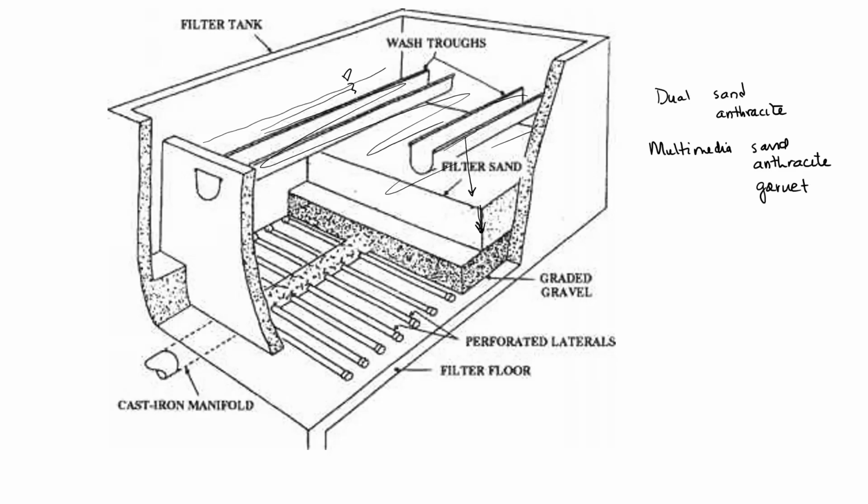And so the water's flowing down through the sand, then through a graded gravel, then into perforated pipes. These pipes are all perforated. And then it is collected and moves on to the next process. You can see it flows into here. Now, I'm going to change colors because that's during operation.